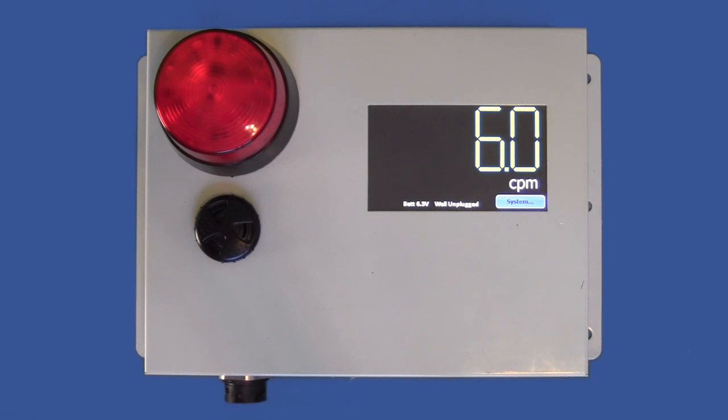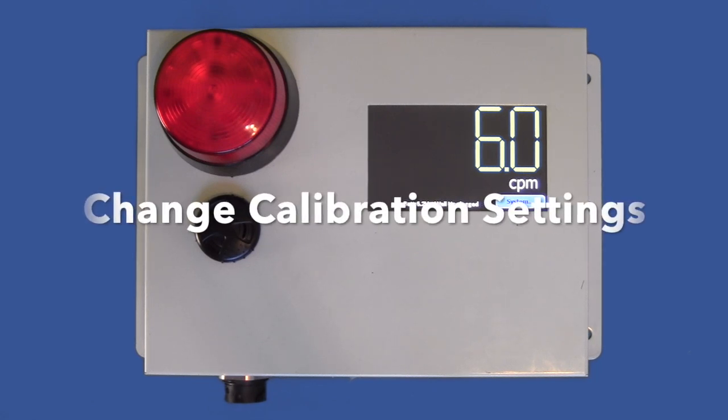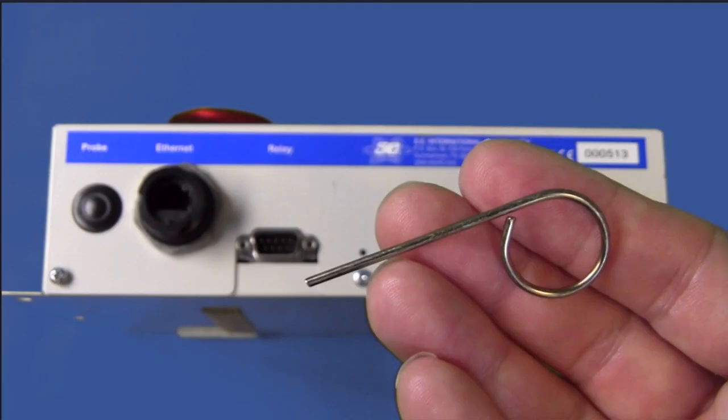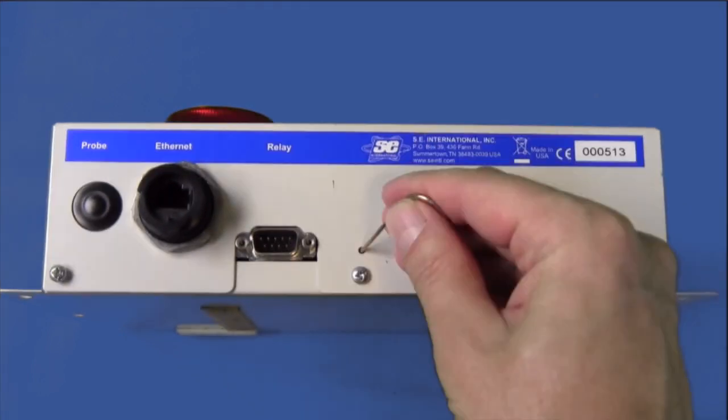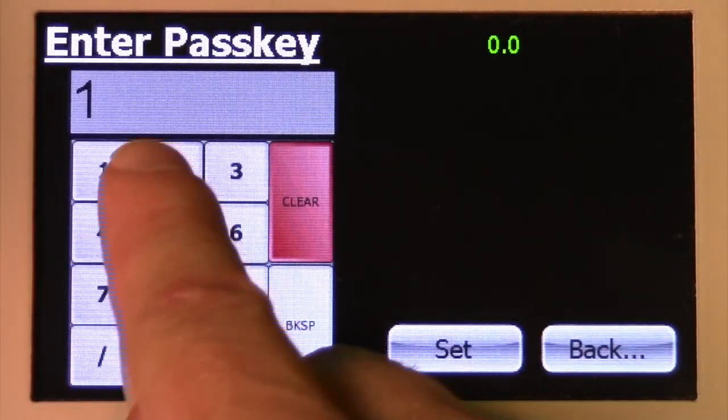I now want to show you how to change some calibration settings via the touchscreen. To enter the calibration settings screen, use the included pin or a paperclip to press the recessed button on the bottom of the area monitor. This will summon the Enter Passkey screen to display. Enter your passkey and select the Set button.